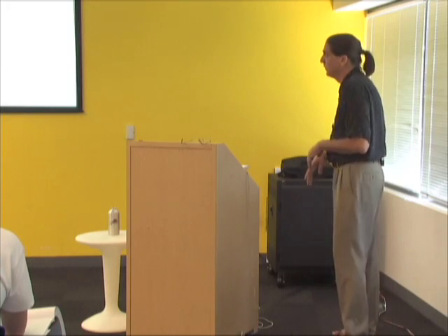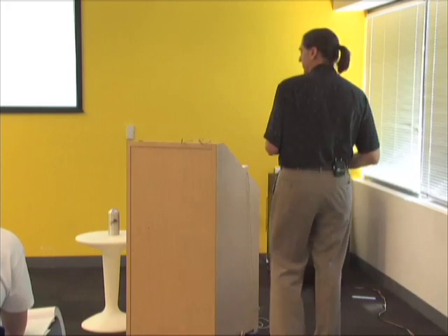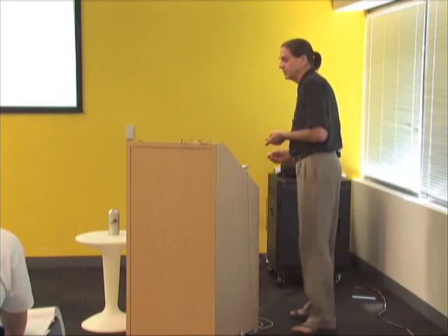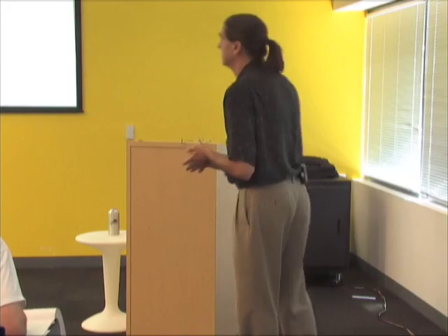The other thing I'm doing, if you've noticed, is my scenes across the top, all those ones with S's on them are sections. So I can go through my model and go back to that section whenever I want to, and all I'm saving on that tab is a section. So I tend to go through a model and set up sections up front.